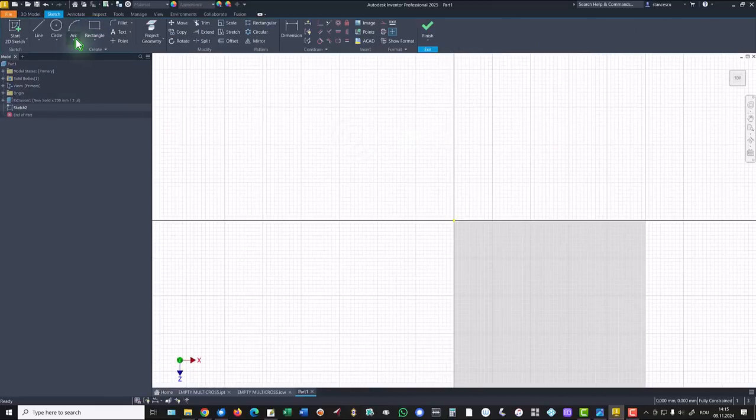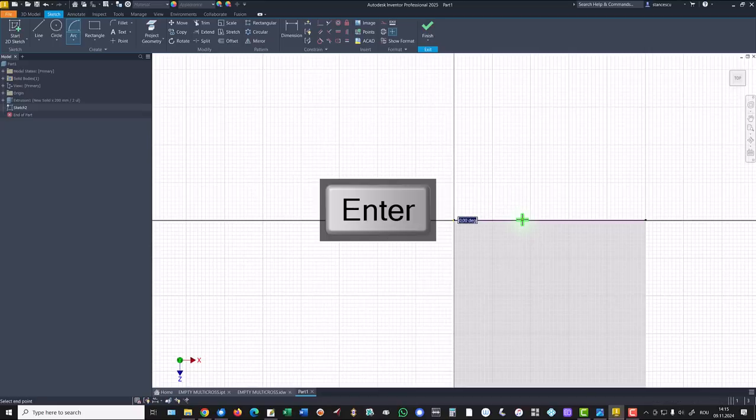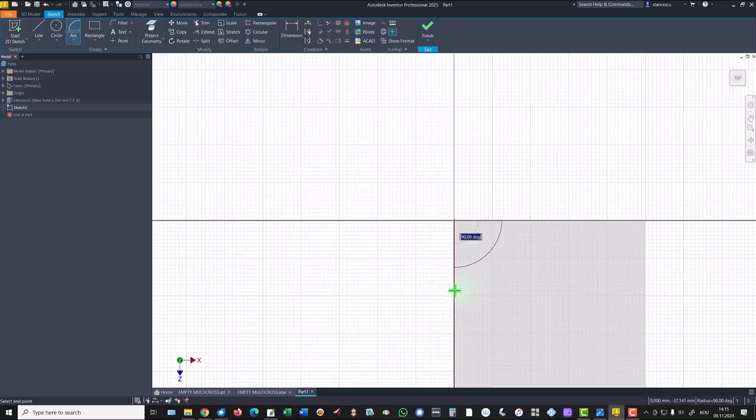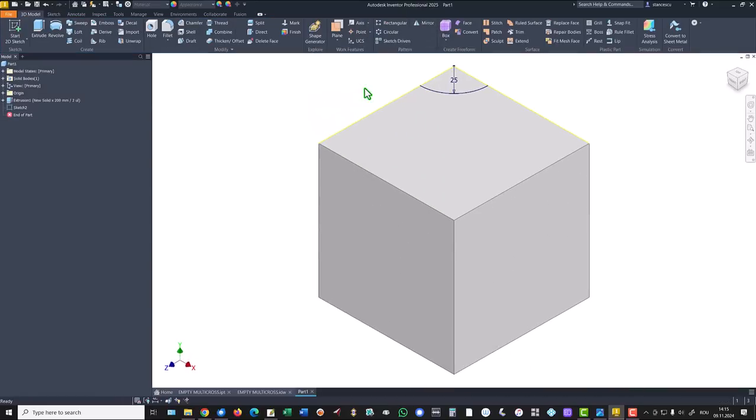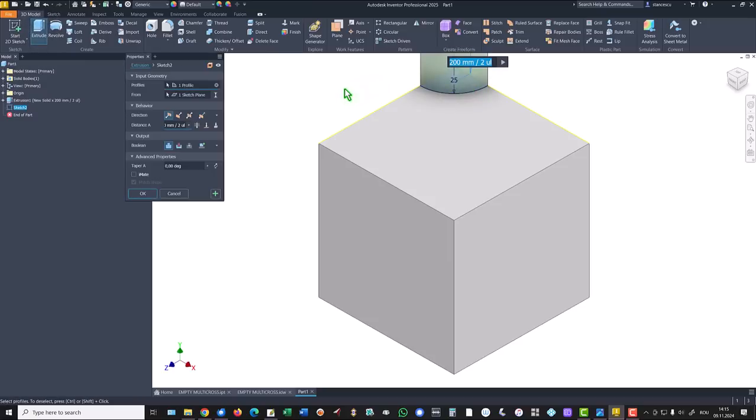The new sketch is based on an arc with this dimension of 50 divided by 2 and going to the vertical. Finish sketch. We have sides, so we can apply extrude on 10 millimeters. This is a random value, not important, you will see this.